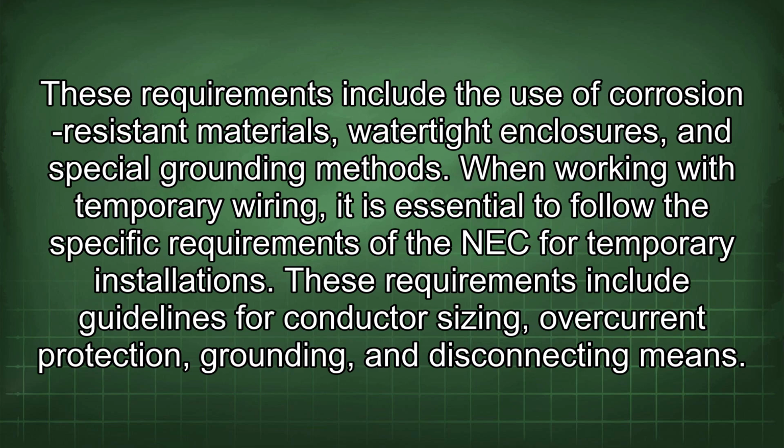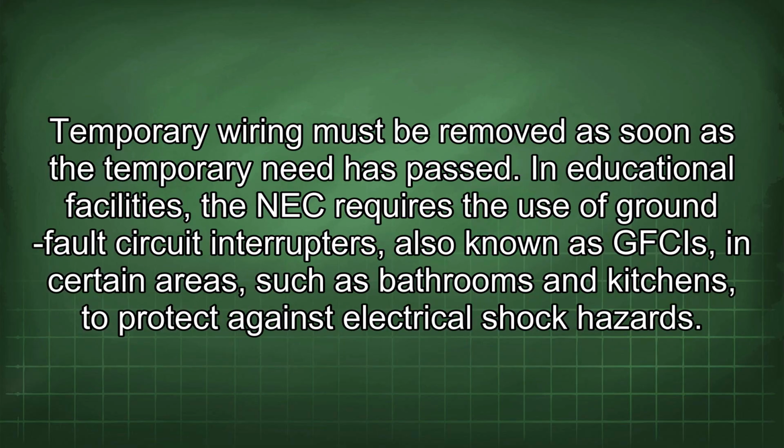When working with temporary wiring, it is essential to follow the specific requirements of the NEC for temporary installations. These requirements include guidelines for conductor sizing, overcurrent protection, grounding, and disconnecting means. Temporary wiring must be removed as soon as the temporary need has passed.